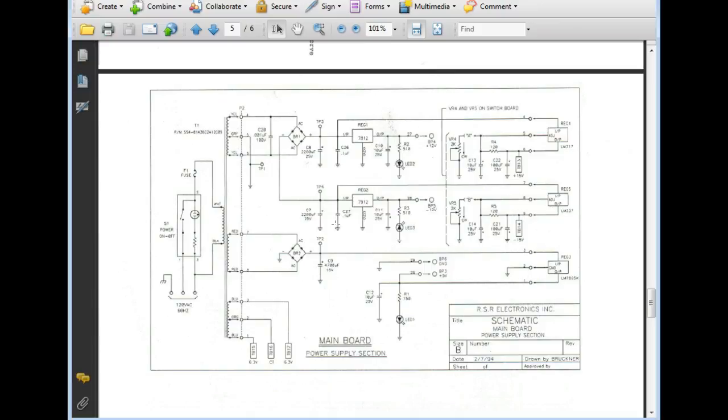Current is going to flow through it. It's going to drop a voltage, and it's going to get hot real fast. And what's it going to do? It's going to blow up, especially in power supplies, because the only thing limiting the current flow into these capacitors is the DC resistance of those transformers right there. So if you put that polarized capacitor in a power supply backwards, it will blow up.